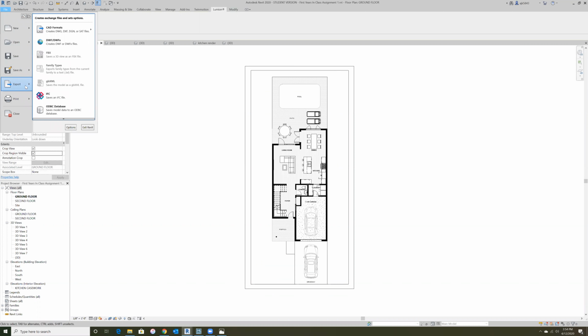In Revit, when you're exporting drawings, you can either choose the option to export as a DWG file or as some sort of image. Really depends on what you plan on doing with it. You can certainly put it in CAD as a DWG and continue to alter the line work or change some things. Since we're pretty satisfied with our design directly from Revit, we're going to export as an image, which will be ready to go as a final drawing, maybe only making some tweaks to it with Photoshop. So that can be found under Images and Animations, and then scroll down to Image.